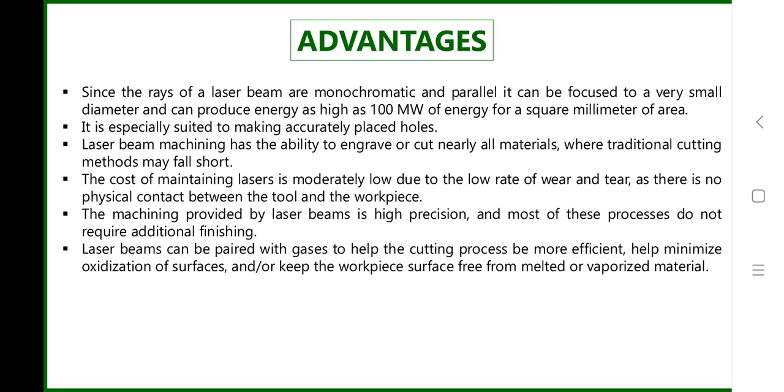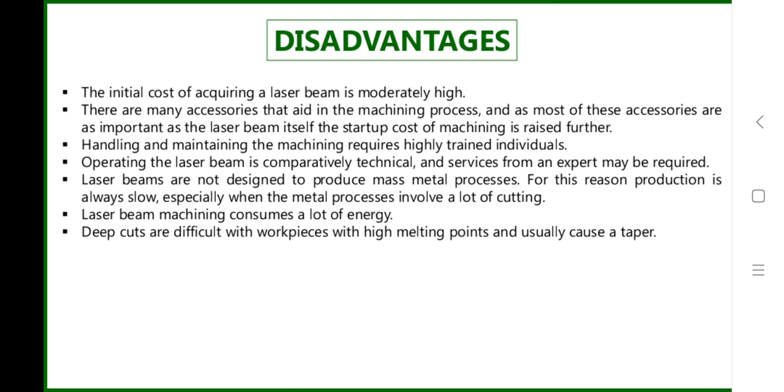The laser beam can be paired with gases to make the cutting process more efficient. They also help to minimize oxidation of the surface or to keep the workpiece surface free from melted or vaporized materials. These are the advantages.